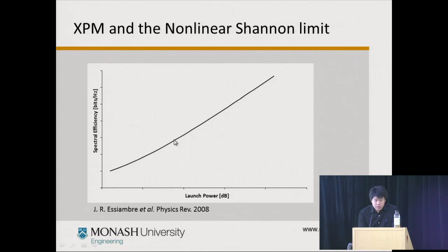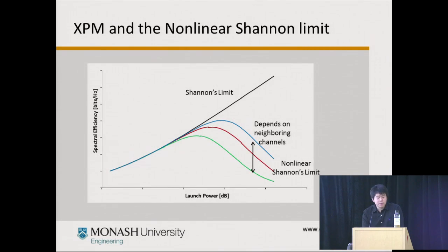And this is governed predominantly by the noise, which is usually modeled as additive white Gaussian noise. However, in the optical channel, because optical fibers have a nonlinear property, which increases with increasing signal power, you cannot indefinitely increase the capacity limit by simply increasing the power.